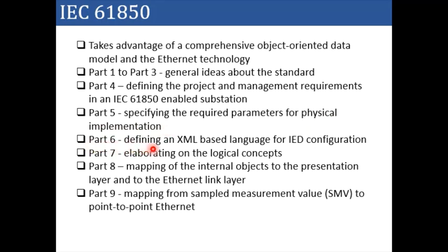Part 6 defines an XML based language for IED configuration. Part 7 elaborates on the logical concepts. Part 8 talks about the mapping of the internal objects to the presentation layer and to the Ethernet link layer. Part 9 talks about the mapping from sampled measurement value, that is commonly known as SMV, to point-to-point Ethernet.